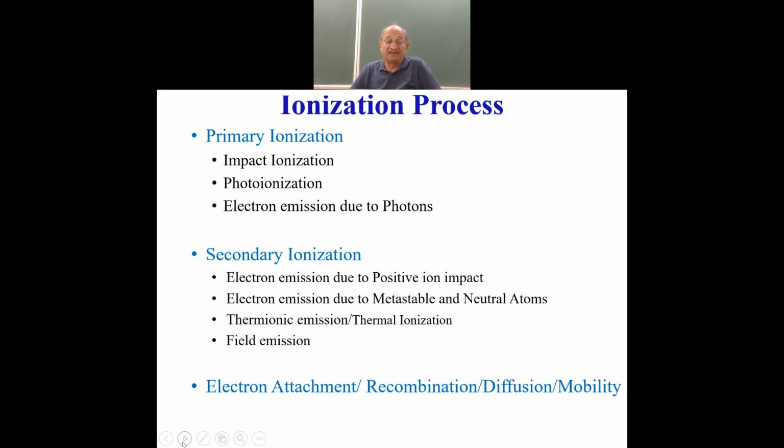So we call it the primary ionization process, that is because of impact ionization. Electrons, which I was mentioning, have a much higher speed because they are lighter as compared to the molecules. They move very fast, and when they make an impact with a neutral molecule, they eject another electron, and the ionization process cascades. You can say it's an exponential process that increases the ionization. So charged particles are formed by one single electron a number of times on impact with the neutral molecule.